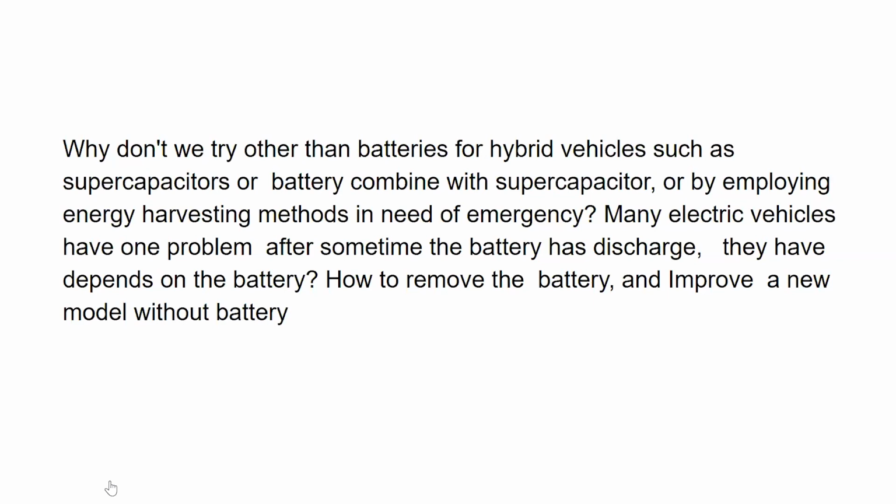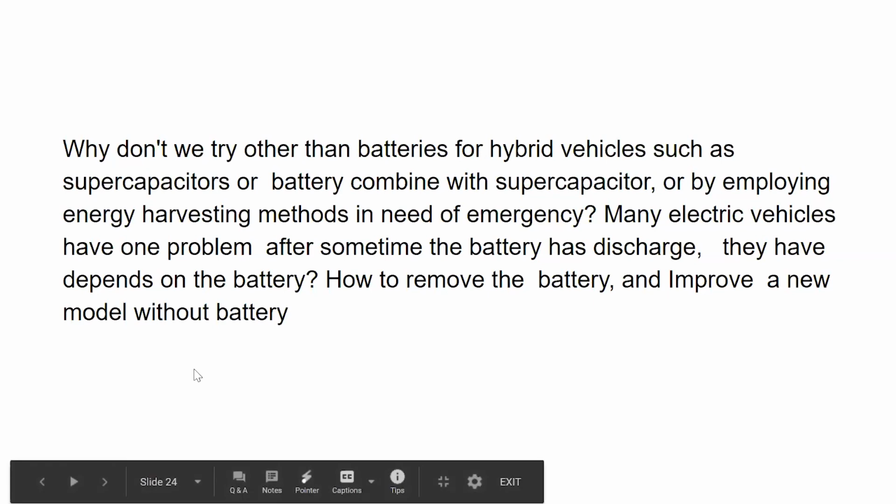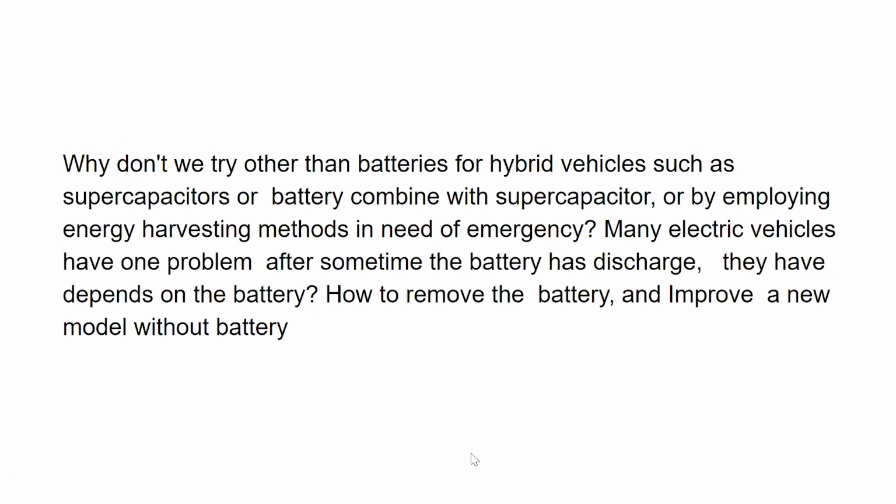So yeah, supercapacitors are also promising, but supercapacitors have very low energy density, meaning they will not provide you the long range that you need to drive a long distance. You need energy, and supercapacitors are good for providing instantaneous power. So it will improve your acceleration if you have a supercapacitor, but it will never improve your range. And when it comes to combining the battery with supercapacitors, I believe there have been some studies, but I'm not sure why it has not happened.